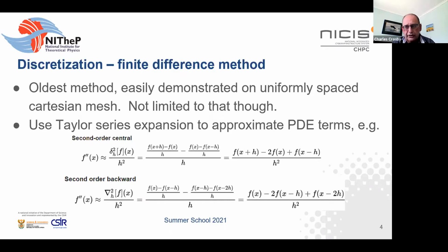With unstructured meshes, where you don't have an IJK structure to the grid, it's not always obvious where the upstream, what the upstream cell is. So second order or higher order upwind differencing schemes took quite a long time to be developed. However, we've got up to second to third order upwind differencing scheme, even on unstructured grids these days. And that would be your workhorse method.